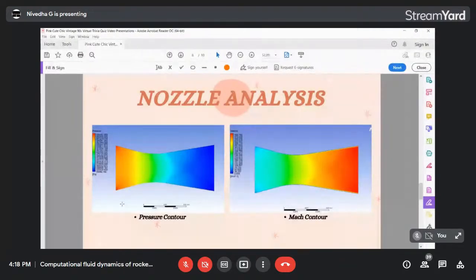Then we go to the solution controls. We have the solution controls, and we iterated for around 5,000 to 6,000 times. During the iteration, you can see a number of residual plots like the nu t, x velocity, y velocity, etc. on your screens, which I don't have here, unfortunately.